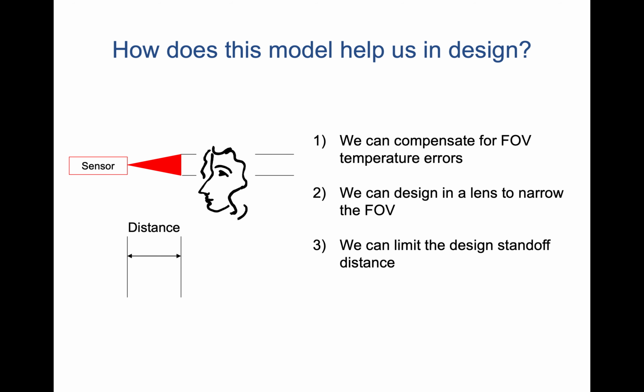Or we could design a lens in, as shown in the schematic to the left, that narrows the field of view and makes it so that we can look at a forehead very far away and still have it fill the sensor field of view. Or third, we can limit the design standoff distance, saying that in our design, the forehead has to be within 1 forehead distance of the sensor.